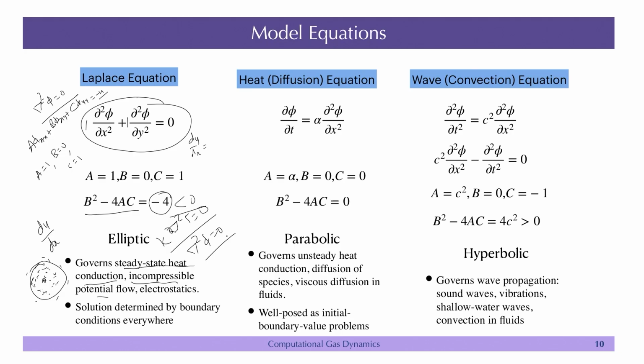So, you need one kind of scheme for this kind of problem, because whatever disturbance or change you make at one point, you expect it to be felt everywhere at an infinite speed. Of course, infinite is not possible when you simulate this kind of problem, but if you are solving it numerically, you have to have a grid where, if you put in a disturbance, all the grid points around it feel the disturbance instantly. You have to have that kind of scheme. The Poisson equation, and the pressure Poisson equation which people use to solve the incompressible equations, also come under this class.